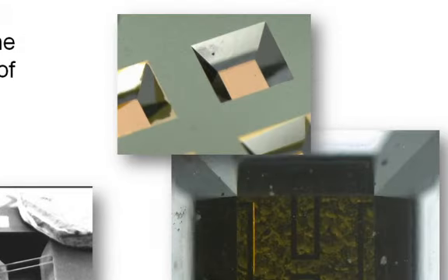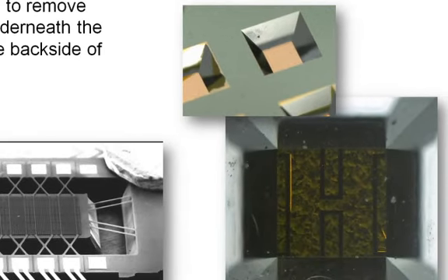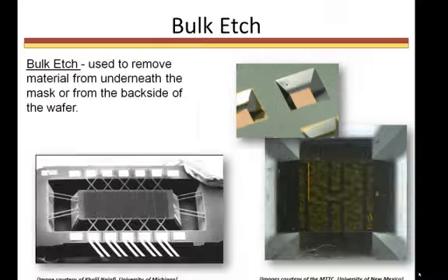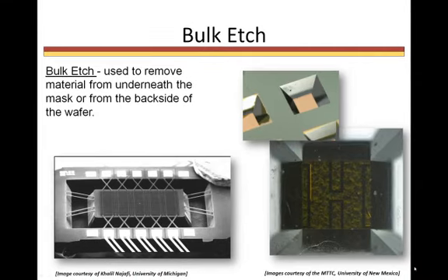This graphic shows the backside of a wafer that has been completely etched through the substrate to a layer of silicon nitride that was previously deposited on the front side of the wafer. The hole in the backside of the wafer is the reference chamber for a micropressure sensor. You can see the electronic sensing circuit on the front side of the wafer by looking through the etched hole. A combination of these processes, surface and bulk, allow for the construction of a variety of electronic and mechanical devices on the same microchip.